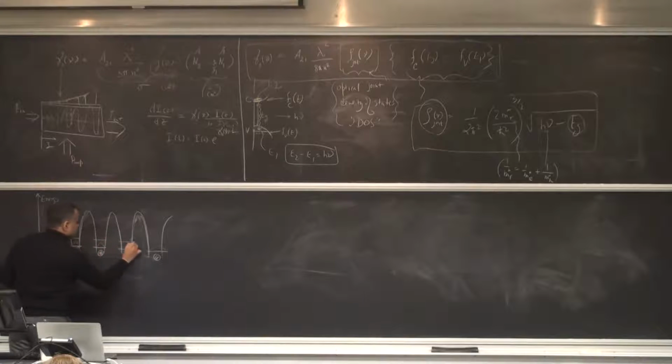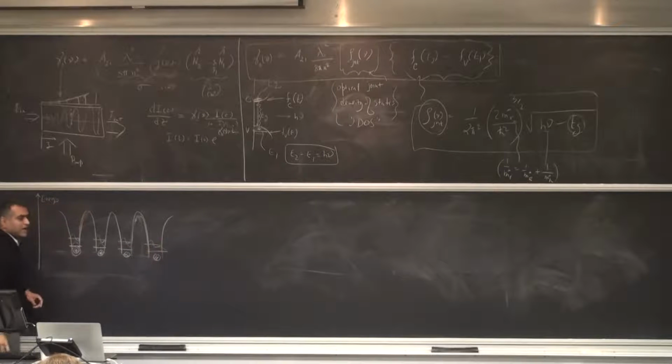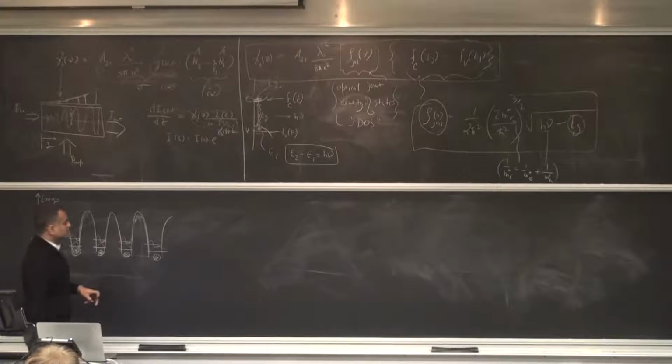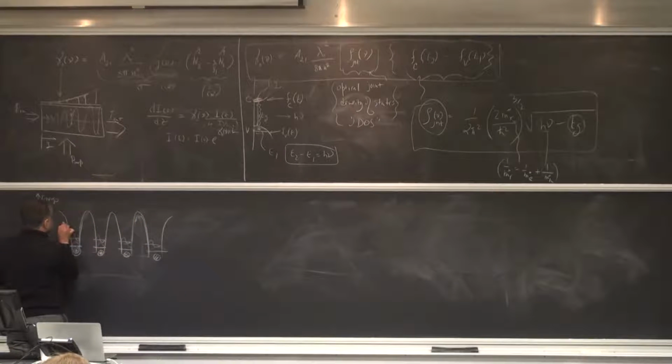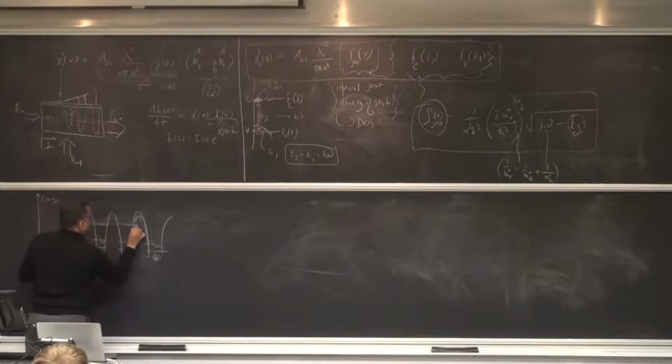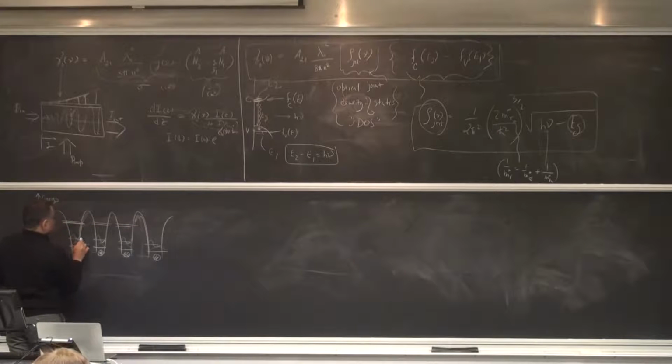And then there may be more electrons depending upon where in the periodic table you are, and these are really bound. They don't form what you call bands. The bands would be the outermost shell of electrons. Typically in semiconductors that we use for lasers, you have 4s or 3s orbitals and 4p orbitals. So as you go up in energy, there are these states that start interacting with each other much more strongly, meaning an electron state here will overlap very strongly with the next state here, and these are the ones that form bands, and they also form the chemical bonds, right?